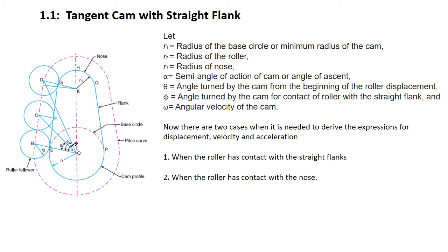Before this type of cam, we first found out the velocity and acceleration and displacement, and then we computed or drew the profile of the cam.